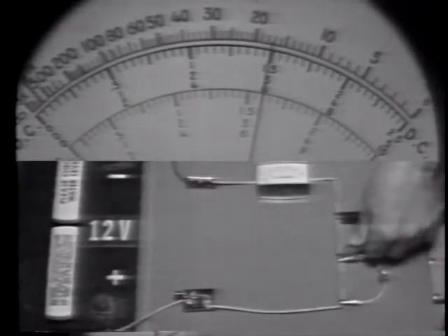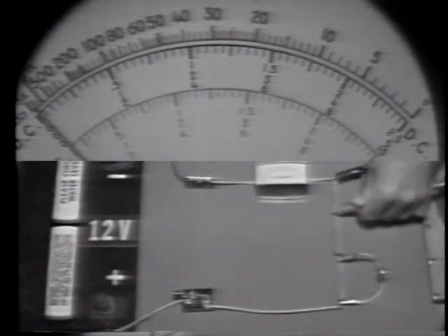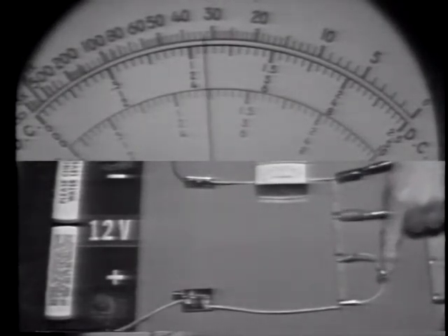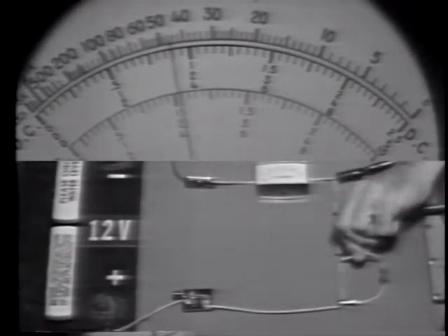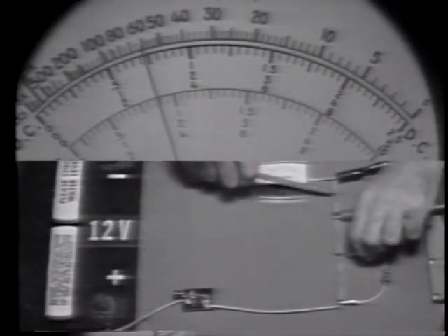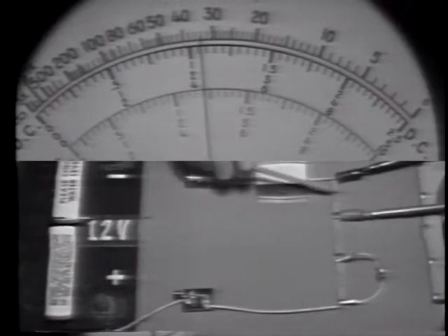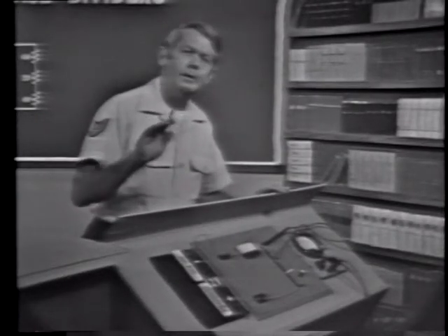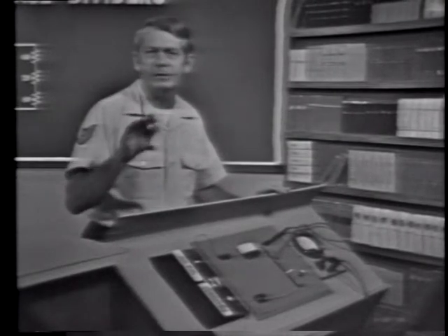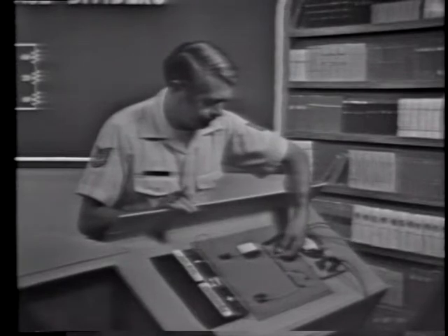Let's go up and check this one, observing polarity as I make the connections. Okay, with the load device connected, the voltage here is a little over 4 volts. When I remove the load device, the voltage here decreases. When I load the circuit, the voltage here increases. Okay, loading the circuit changes the voltages in the divider. Let me remove everything and we'll figure out why.